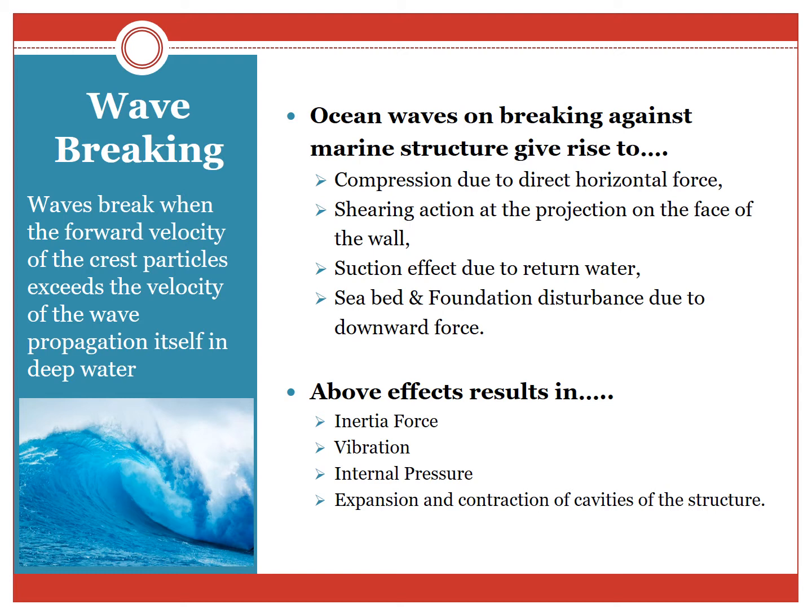Normally, by these effects, some may result in inertia force, vibrations, internal pressure, and expansion and contraction of cavities of the structure. Now, the internal pressure on the air in the pores and the cavity of the structure is equal to 3.5 times the pressure of water on the face of the wall. In case of a masonry structure, these forces have a severe damaging effect. Whereas if it is a mound type of structure having numerous voids, the internal pressure gets relieved itself.